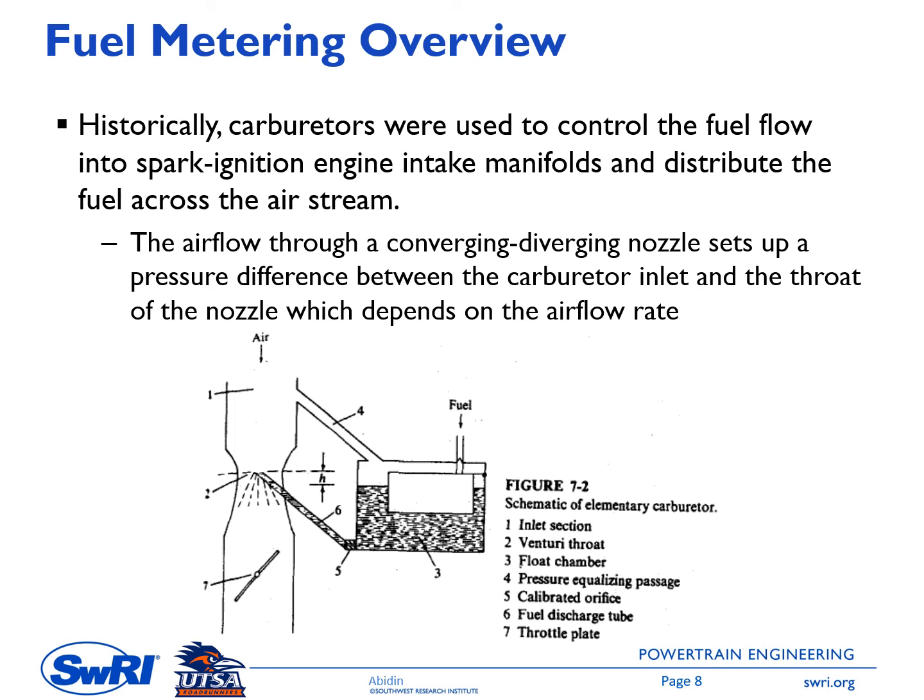This figure shows the schematic of the carburetor. This is the inflow of fresh air, and number 1 here is called the inlet suction, and part of this inlet suction is connected to this component through pipe number 4, called the pressure equalizing passage. Number 2 is the venturi throat. The principal work of this carburetor is similar to the phenomena in a nozzle diffuser.